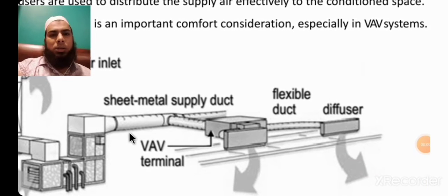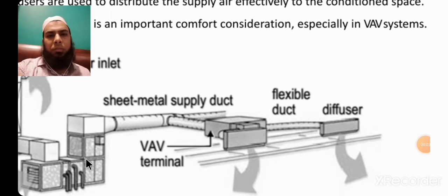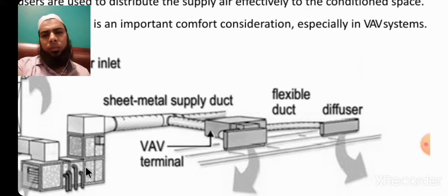But normally in Pakistan we don't have a desiccant wheel or reheat coil in many normally used buildings, like malls and supermarkets. But in pharmaceuticals, where we have a particular standard of humidity, we need to place a desiccant wheel or reheat coil and send the accurate amount of humidified and temperature-controlled air.